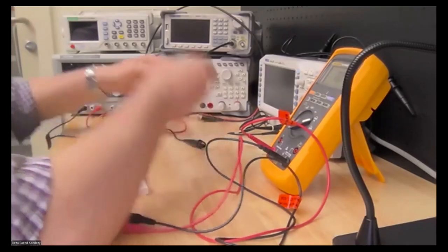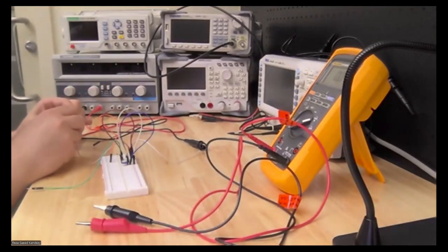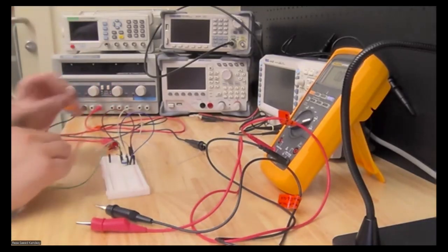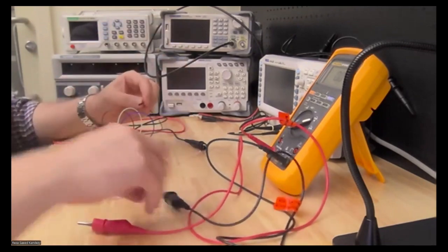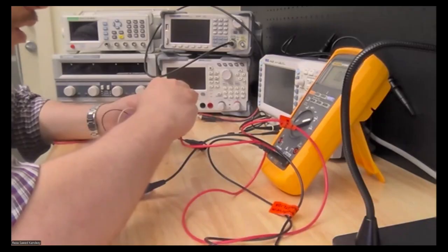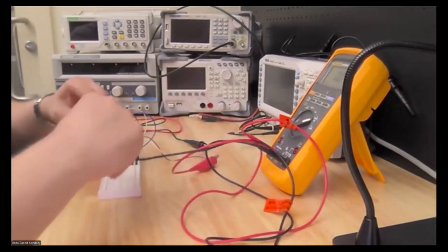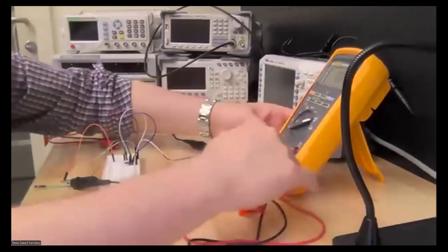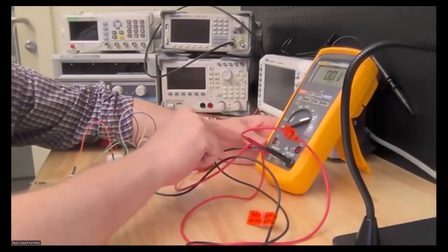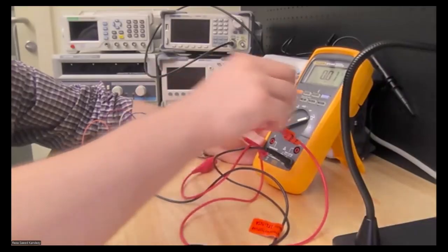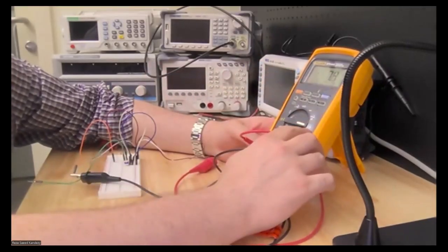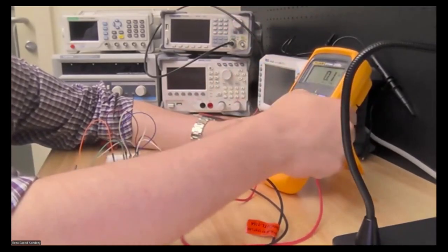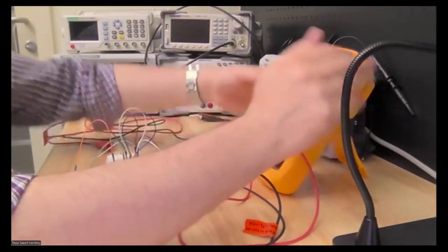So I am gonna connect my voltage source, and I want to measure the current that is applied to my base, so I make sure that I actually have that amount of current. Now I am expecting microamps, so I'm gonna put the probe on the microamp socket and set the multimeter to microamp. Again, the default is AC, so you need to change it to DC. Now it is microamp DC.